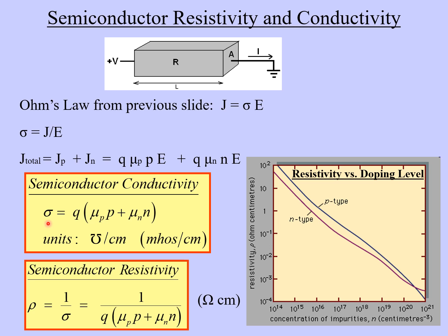So the units of conductivity are 1 over ohm-centimeters. And when you have 1 over ohms, there's a couple different ways to show that. They sometimes show it as an omega symbol, which means ohms, right? But it's upside down, so that tells us it's the inverse of omega. That's also called a mho. And if you notice, mho is just ohm spelled backwards. So these are just a couple of clever ways to describe conductivity. It's mhos per centimeter is the unit of conductivity.